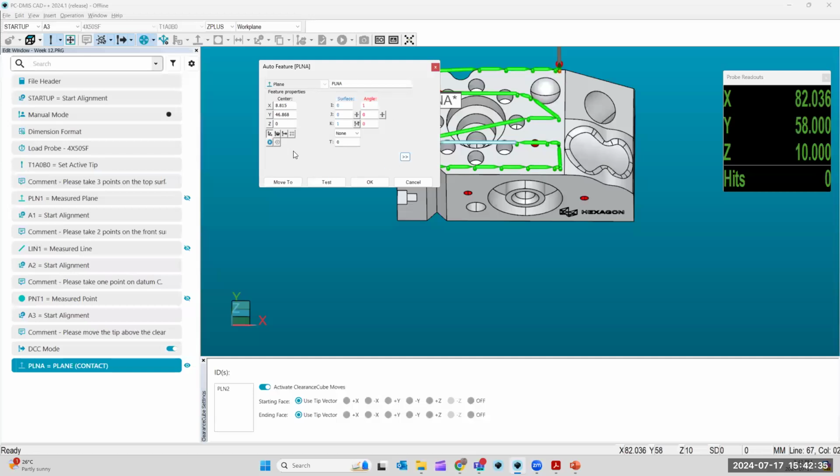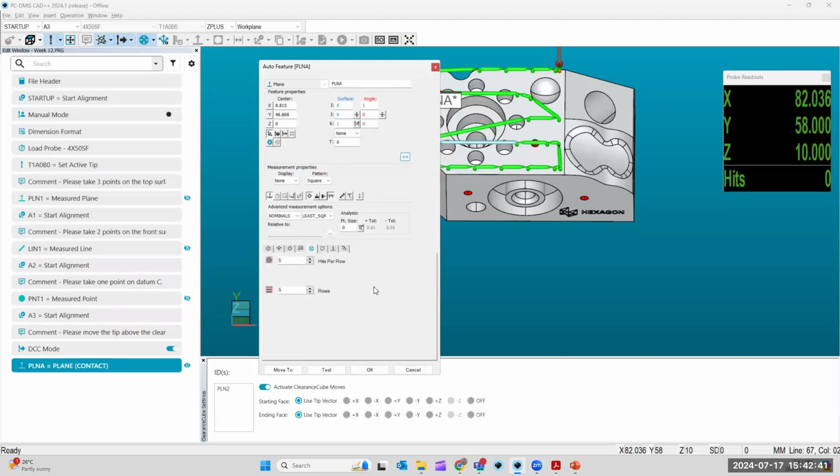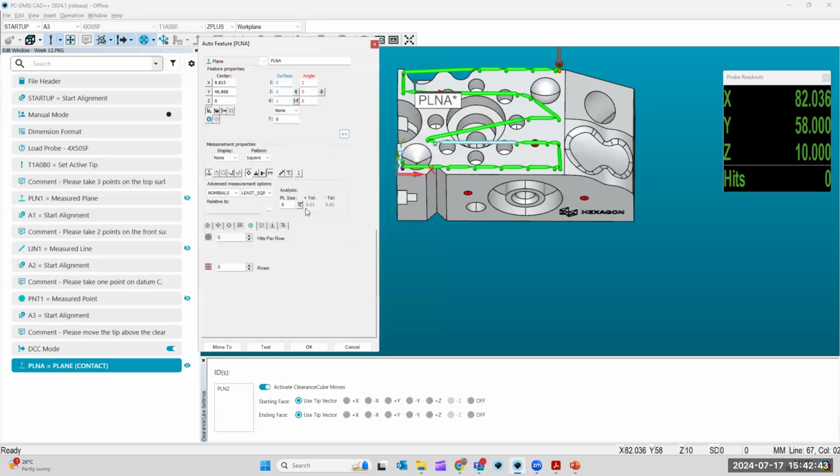Now, if you see this and you don't see more settings underneath it, you click Show Advanced Measuring Options, and you can change a lot of features here. My favorite settings to change are the little anchor. I like to see this one on auto wrist, which means it's going to automatically pick your tool angle that's appropriate for that feature. There's times where you don't want that and you override it.